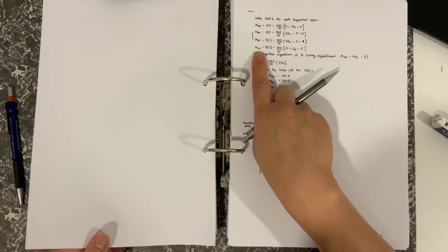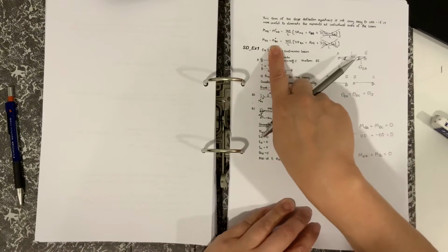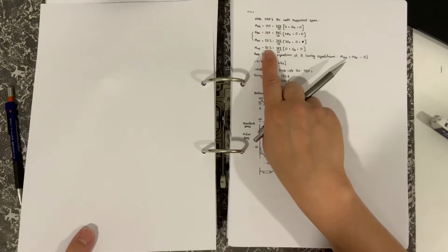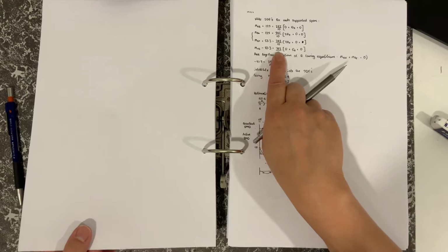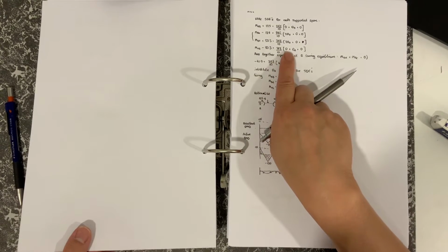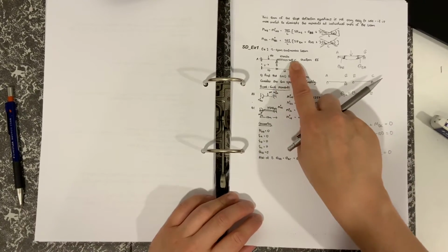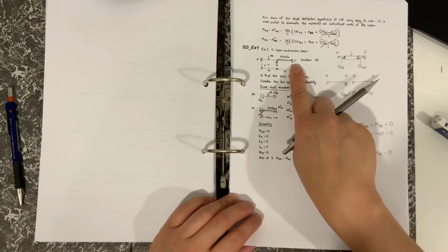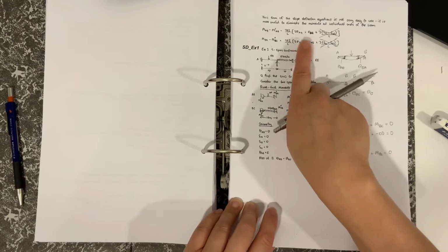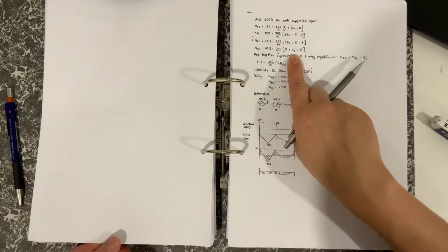And the last equation, MCB minus MFCB. FCB is 83.3, so minus 83.3 is equal to 2EI over L, which is 10, and that's going to be equal to 0 for the CB, because there we've said theta C is equal to 0, plus 1 of theta on the other side, which is going to be theta B.